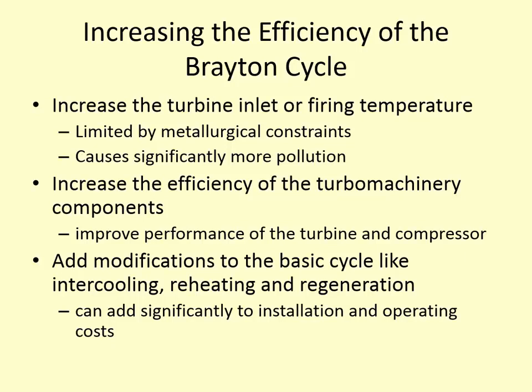So the machinery components themselves, we can seek to make them more efficient. So we improve the turbine, improve the compressor. And then another thing we can do is add modifications. So you remember before when we were talking about the intercooling, reheating, and regeneration on steam power plants, that was in chapter 10. Well, we can do the same thing for gas power plants as well.